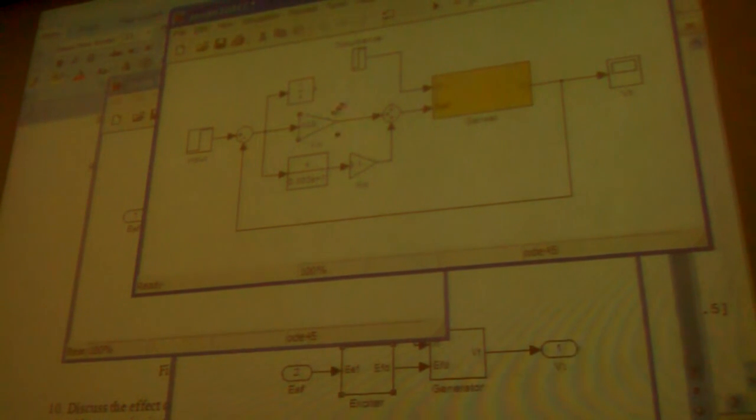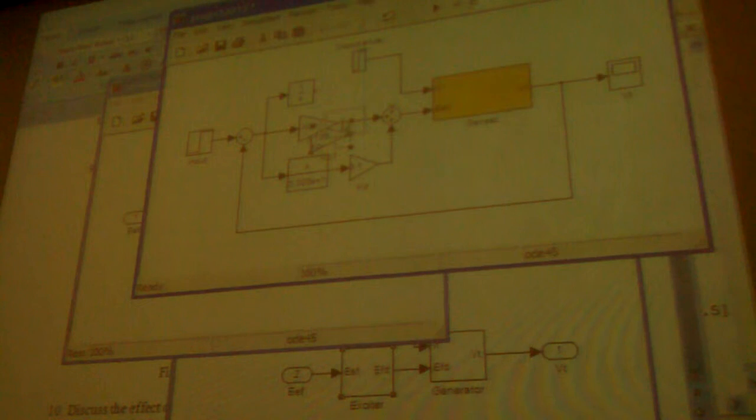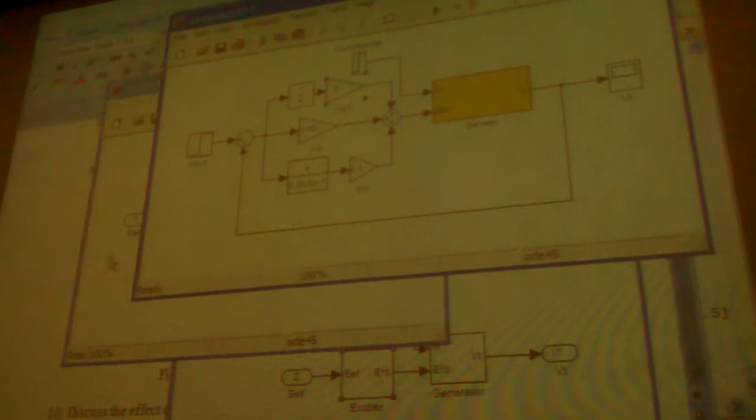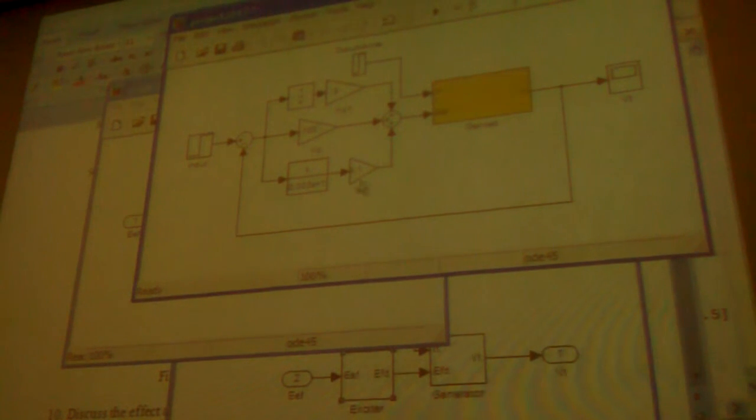And I'm going to multiply by a gain. So KP is 100. Copy and paste. Before I go further, I'm going to verify quickly with you guys. Let's make KI temporarily 0, so it's still a PD controller. Now if you run this, it's 0.1.